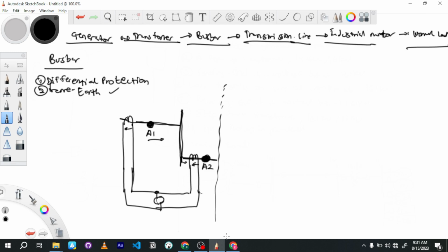So you see, this bus bar is usually a metallic bar. So you need to place some sort of covering around it, some sort of insulation, so that the metal bar doesn't touch ground. If it touches ground, everything is off. You understand? So it involves measuring the fault current from the switchgear frame, the frame of this one, to the earth.